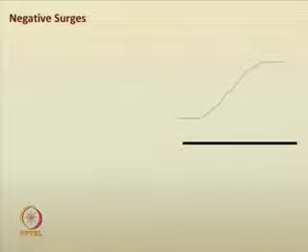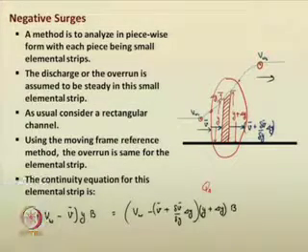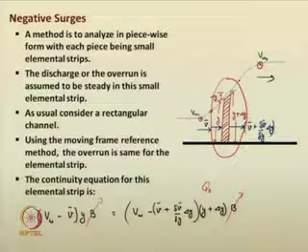So, I can write it further now, for the same elemental strip, y plus delta y. Just rearrange the terms here, and you can see that V w minus V bar into y, this b can be cancelled off. We have not incorporated density here because we are considering incompressible flow. For that reason the density gets cancelled off automatically.